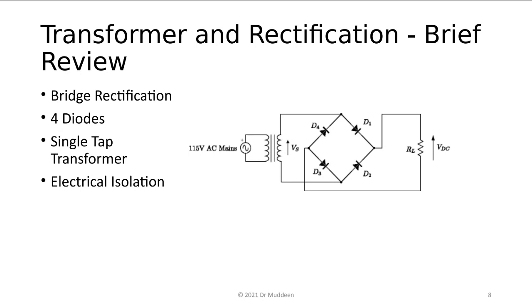You have to be very careful in a situation like that, because if certain things happen in the power supply, you can get mains voltage coming across. Or equally well, if something happens on the mains side, you can get the power supply being subjected to mains voltage as well. All right. So, just throwing it in here for electrical safety, transformers with separate coils for the primary and the secondary give you a measure of electrical safety.